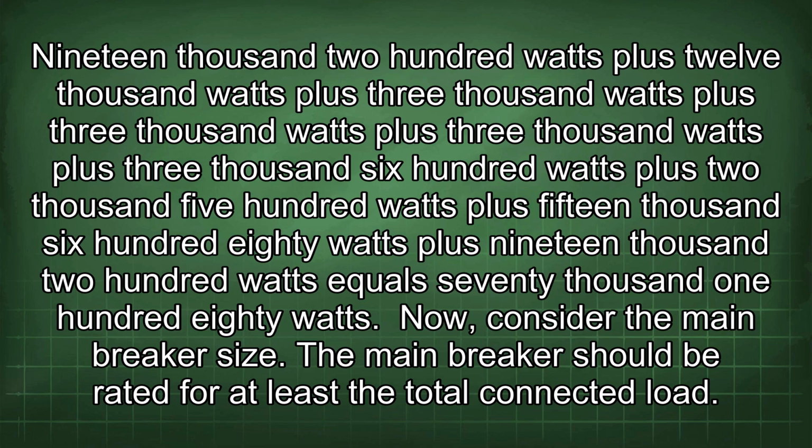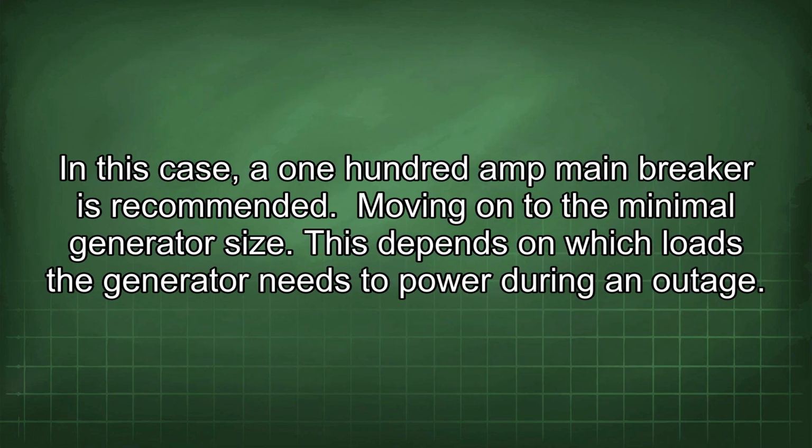Now, consider the main breaker size. The main breaker should be rated for at least the total connected load. In this case, a 100 amp main breaker is recommended. Moving on to the minimal generator size.